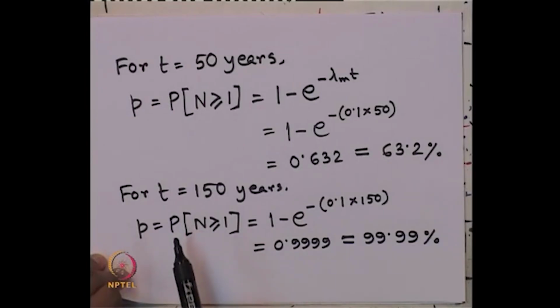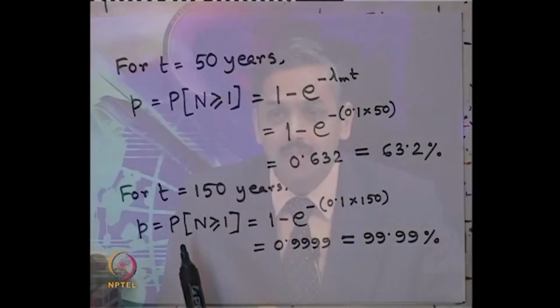But remember, this is the unbounded Gutenberg-Richter equation. So, that is why this magnitude of 9.3, which is very much on the higher side, should not be blindly taken. It should be modified with respect to the upper bound of the Gutenberg-Richter, or bounded Gutenberg-Richter analysis, which is not done for this circum-Pacific belt.